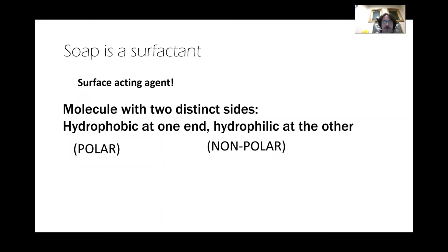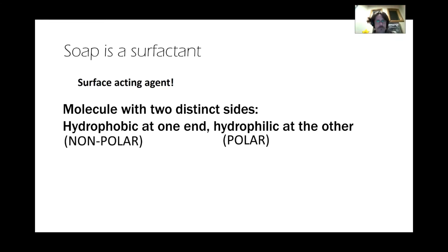One thing to remember is soap is a surfactant. If you don't know my background, I came from the semiconductor industry before academia, where I worked on solving yield limiting problems in making chips. A huge problem was getting rid of residue from the various processes, so there were many, many clean steps, and surfactants are a very important aspect of the semiconductor process. Cleaning the wafers between steps is huge, because if I have photoresist left on my wafer and I try to deposit titanium, I'm doomed.